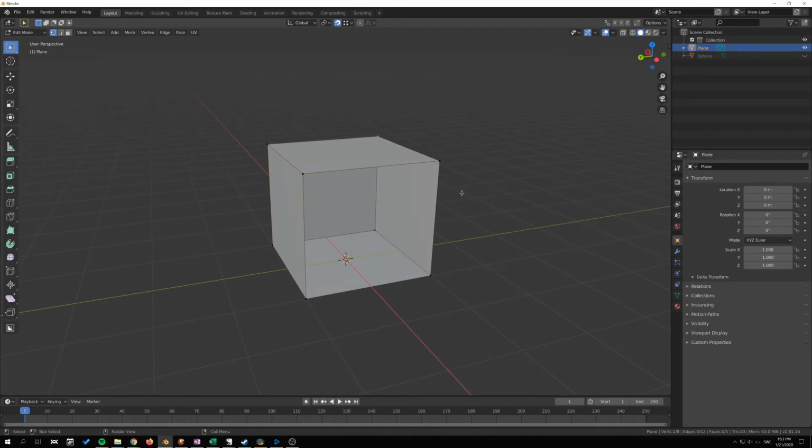You can also use it if you have imported some geometry or some object that someone else made, like a photo scan or something, and it's just full of errors in the mesh. You might want to try merge distance to merge some of those vertices and try to repair the mesh a bit. So it can be used as a kind of a repair tool.